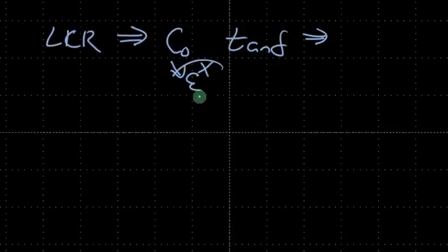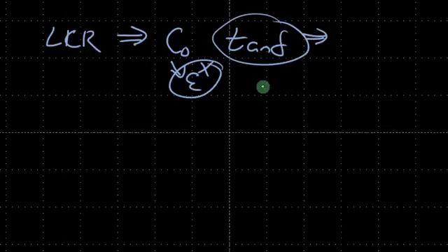And from those, you can measure the permittivity. Basically, if you compare the permittivity and the loss tangent of each of these materials, then you'll be able to understand whether these materials are the same or not. The permittivity and the loss tangent depend on the piezoelectric, elastic, and dielectric properties of the material. Because these parameters all relate to each other, just measuring these two and comparing them between two different samples of the same composition, the same batch, you can tell which one is similar. I actually found that there is some dissimilarity in batches. So that's something you may want to consider before starting an experiment, depending on how similar you want your results.